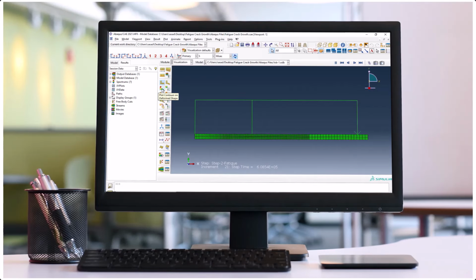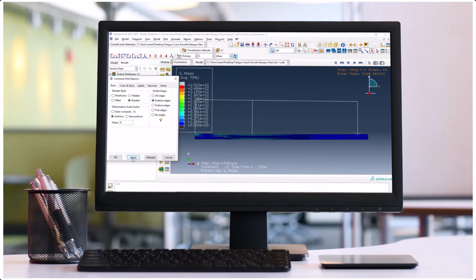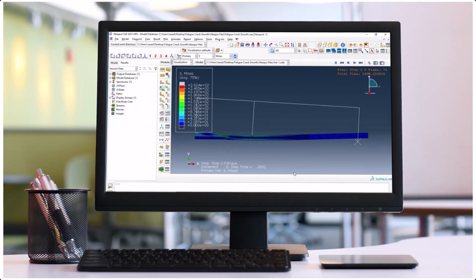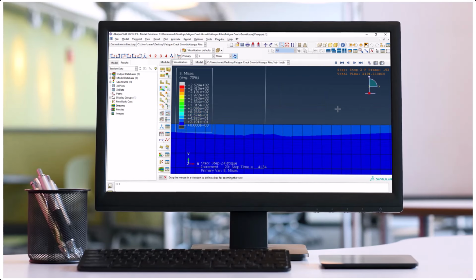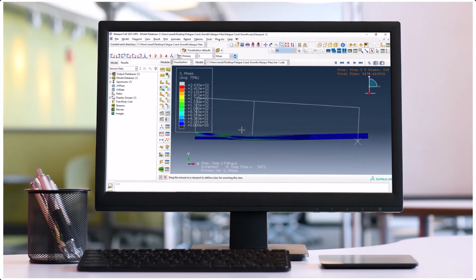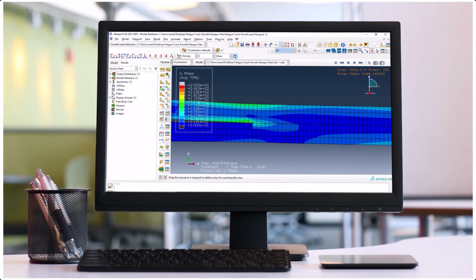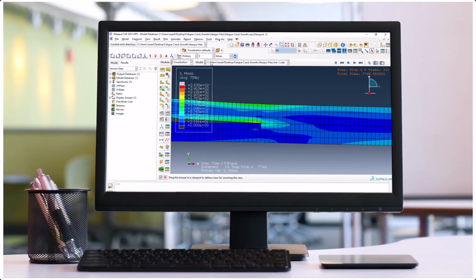In Workshop 6, we provide a step-by-step guide for simulating delamination propagation in low-cycle fatigue analyses using the VCCT method and Paris law. The example includes a rigid loading arm and 2 Lagrangian specimens, where the upper specimen is subjected to periodic tension. For clarity, all required details for implementing the low-cycle fatigue analysis are presented in the provided PDF. Moreover, the video tutorial shows in full detail how to model the components, edit keywords, submit the job, and extract the results.